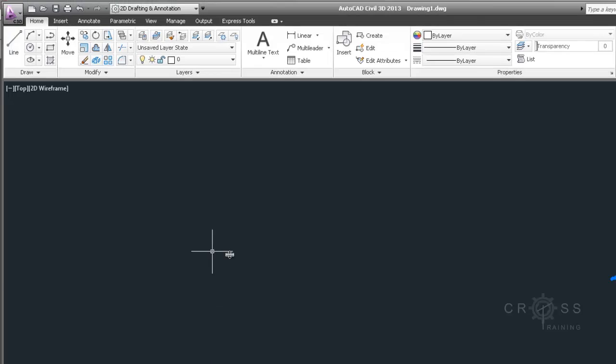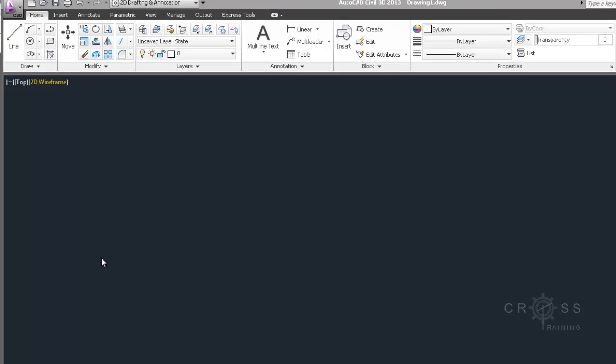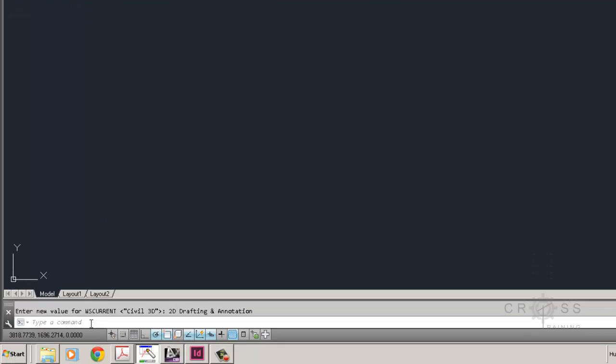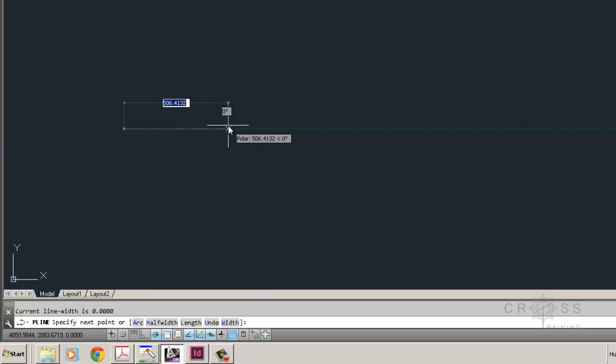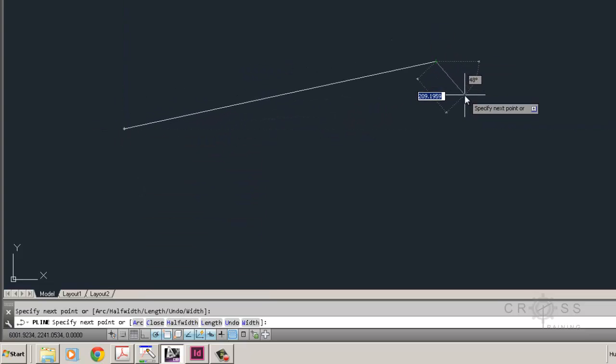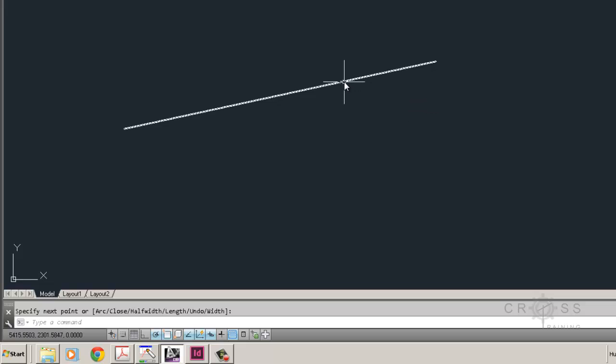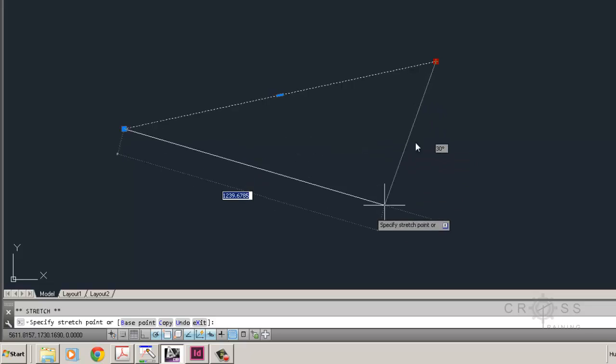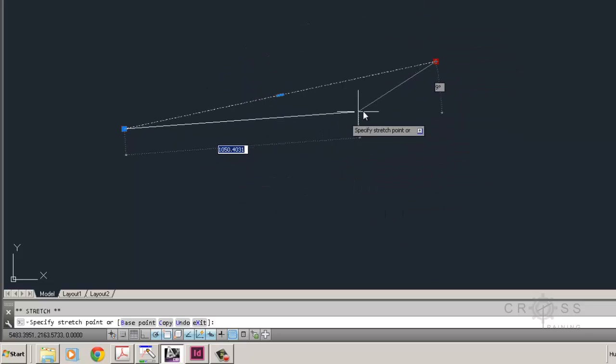We switch back to CAD, get rid of my screen sketches here. Down at the bottom, we have a command line, and I can type in P-line. Now you notice that we are in a polyline command, so if I click and then press enter, we have a polyline, and when I click on it, it's editable because we see little handles here which will allow me to change it. It even tells you the width in here, which is pretty handy.